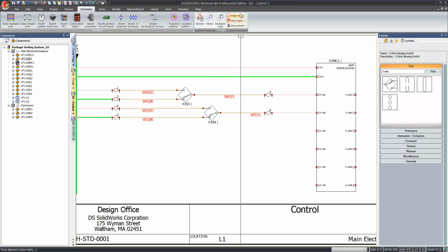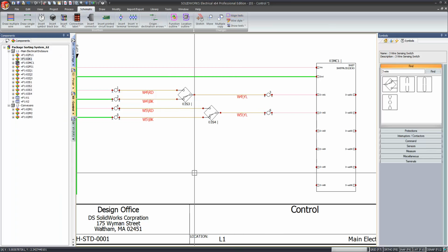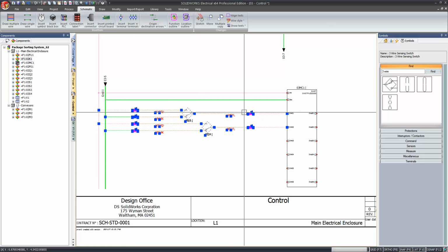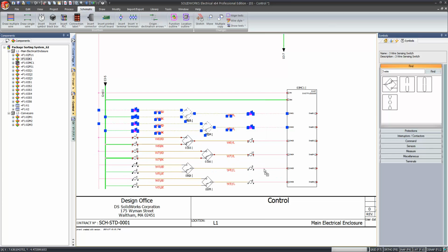And then just keep everything nice and neat. Just drag a big box around those texts, create a vertical line, and center the text on the line. You've got a neat looking 2 circuits that are very easy to copy now. So select, hold down the control key while dragging, and then release, and then do it again. Drag, hold down the control key, and release.